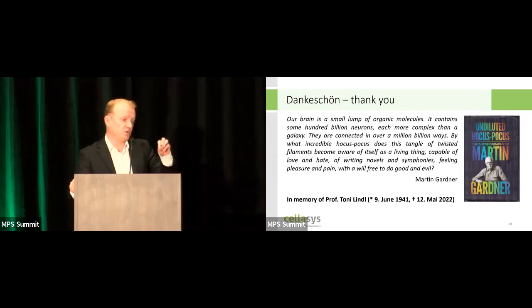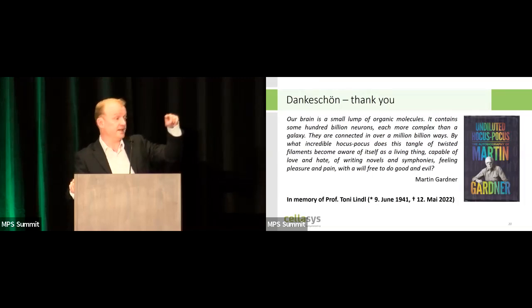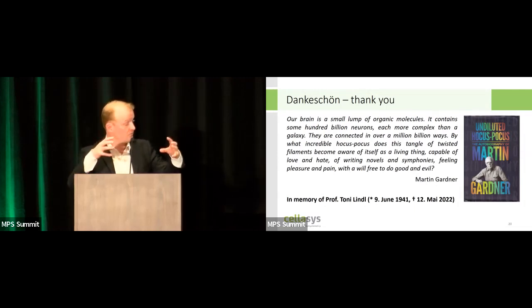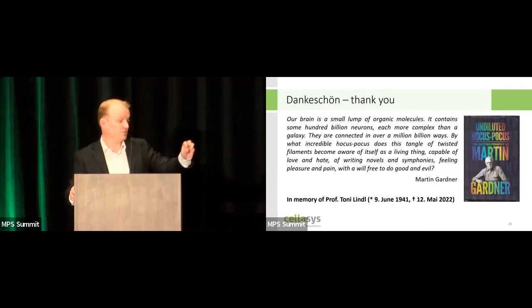So what we do, we run our fluidic system in a stop and go mode, meaning we pump fresh media towards a cellular model for 5 minutes, and then we stop. And then in the next 5 minutes, we can see the acidification rate of the small volume we pumped there. And then we pump again for 5 minutes, so we have fresh media on the chip. We can use that to recalibrate the sensors. Then we stop again, measure for the next 5 minutes, and so on.